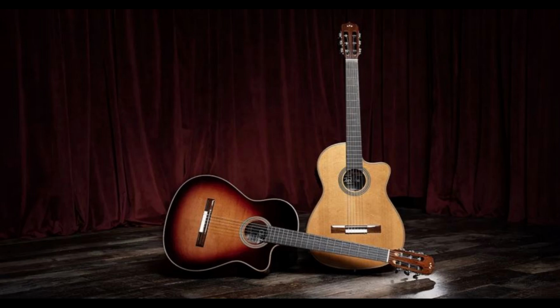During final construction, a small section of the outside corners is carved or routed out and filled with binding material on the outside corners and decorative strips of material next to the binding, which is called purfling. This binding serves to seal off the end grain of the top and back. Purfling can also appear on the back of an acoustic guitar, marking the edge joints of the 2 or 3 sections of the back. Binding and purfling materials are generally made of either wood or plastic.